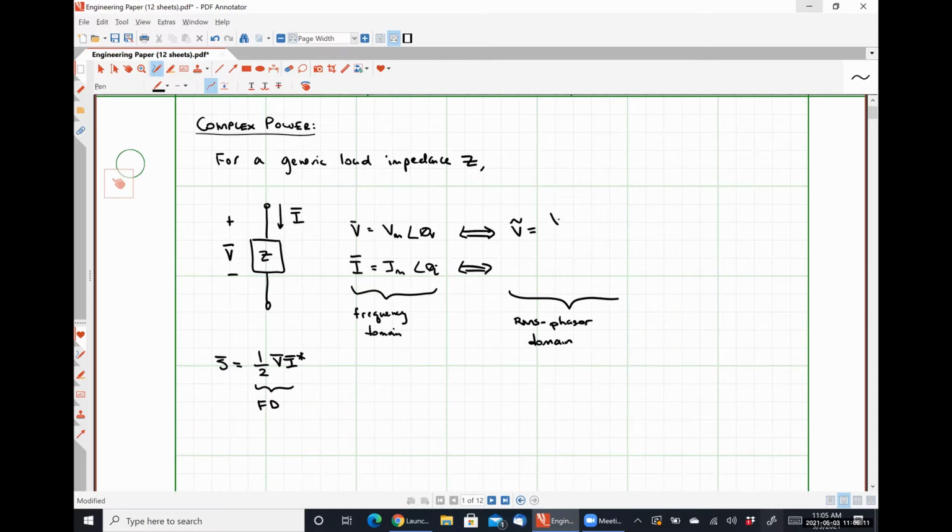And this, by definition, is simply the phasor voltage divided by the square root of 2. So it has some RMS magnitude with the exact same phase angle. And I can do a similar definition for RMS phasor currents, like so. This allows us to write our complex power as the RMS phasor voltage V times the complex conjugate of the RMS phasor current I. So our complex power is simply the multiplication of 2 simple complex numbers, where this is in the RMS domain.